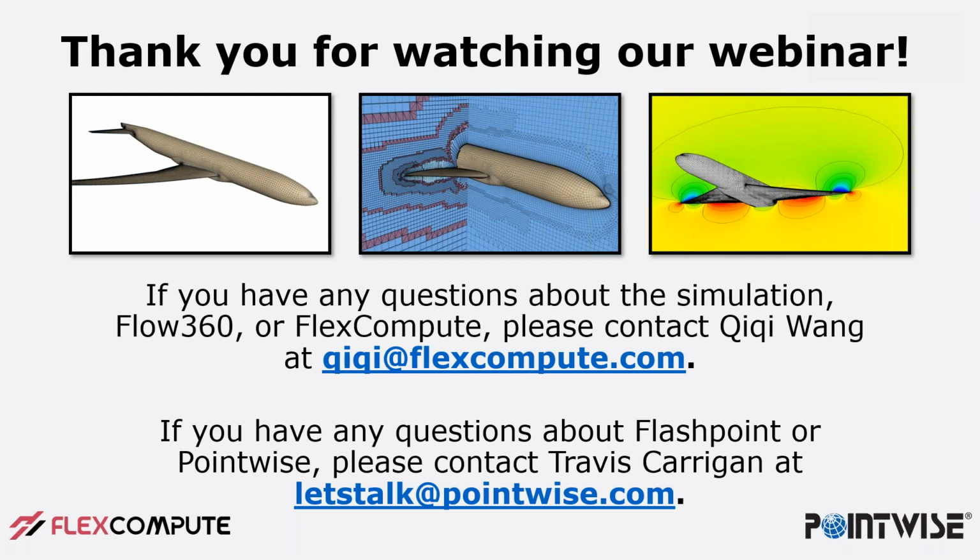But if you have created volumetric sources for controlling even more of the resolution on the surface, because you can create a sphere or a box or any sort of primitive shape as a source in Pointwise and have it pierce the surface, the surface mesher will see that and influence the surface mesh resolution, and it'll also see that in the volume. So these volumetric sources can now impact the resolution of the surface mesh when being created automatically, and they can affect the volume mesh.